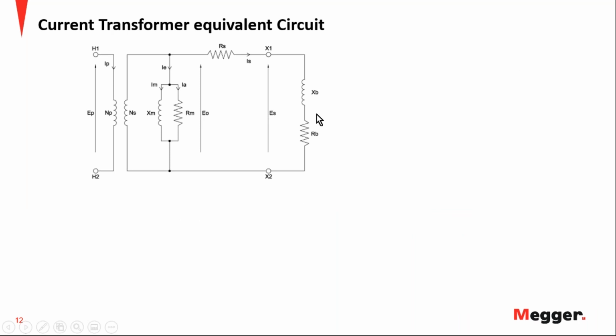we have that there's no losses, and then whatever primary current that we have, represented in terms of the secondary side using the number of turns, should be represented as secondary current without any deviation. So it will be the same, a proportional magnitude, and it will be with no phase deviation.